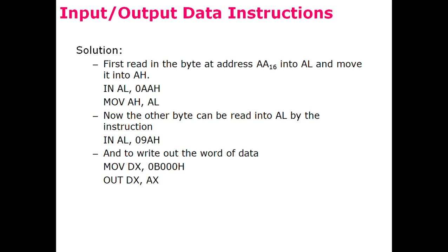If it would be working in the memory mapped I/O type, then any other instructions used for data transfer, like MOV and others, would also be used for the input and output transfer. But most commonly, the isolated I/O type is used for data transfer to input and output devices, and IN and OUT instructions are used to send and receive data from the input and output devices.